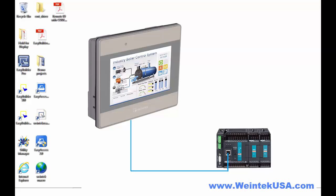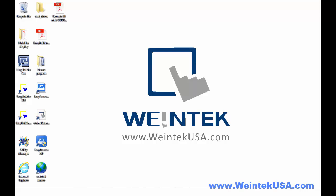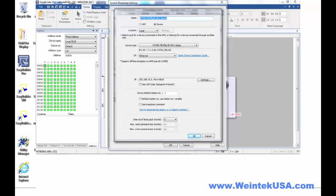Here we have an example of the most common configuration. You've got your HMI and your PLC. In this configuration, there are two IP addresses that need to be set. You need to set your PLC IP address, which is done in System Parameters under the Device tab.